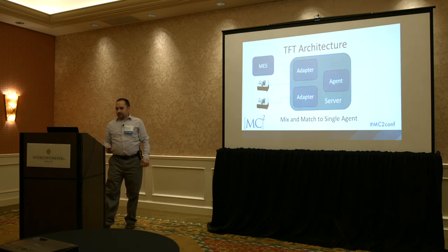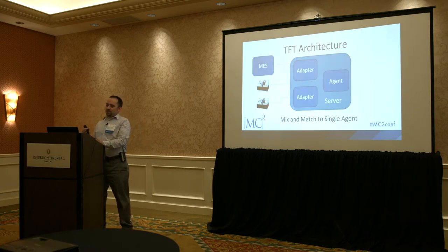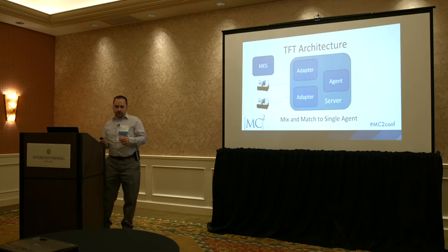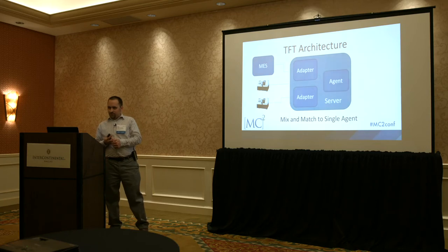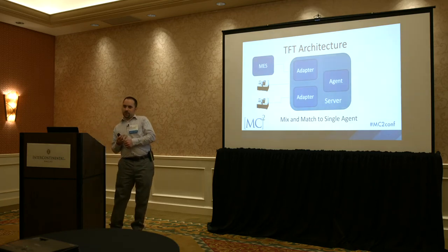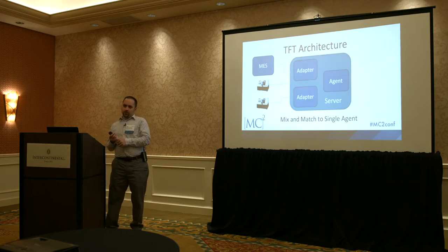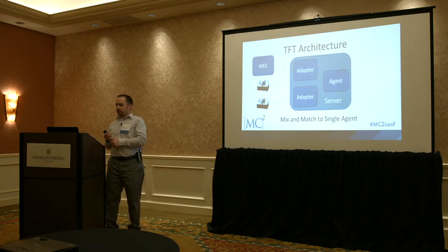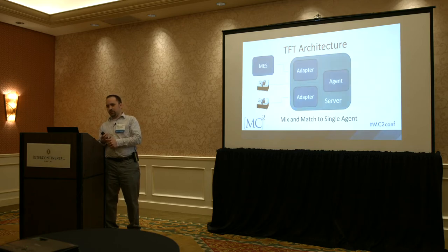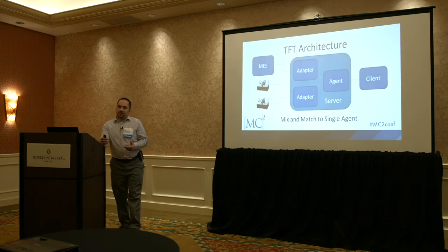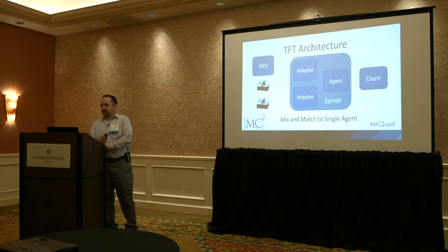That's connected to the adapter? Yes. So I have an adapter that is looking at the data from the MES and feeding that into the agent to carry operator information, what job's running, when we have operators report part counts so we can see what they're reporting for scrap. And when a machine is in downtime, we can have the operators say, okay, we don't have any material, or there's nobody actually here to run this machine, et cetera. That all gets piped through that adapter into the data stream, so that when we're collecting in our client application, it's all aggregated inside of that agent.